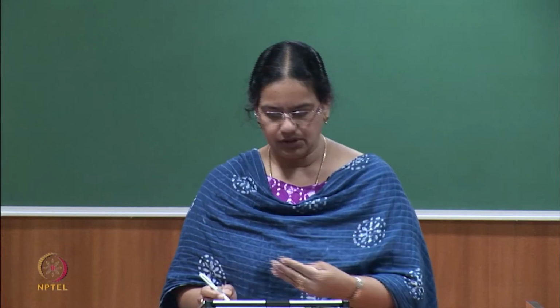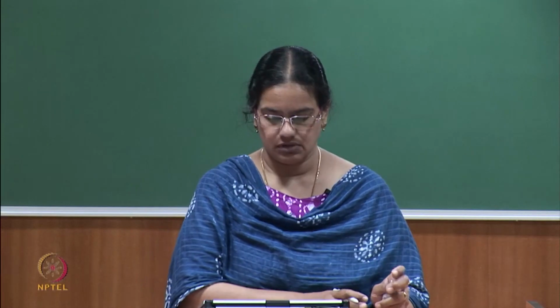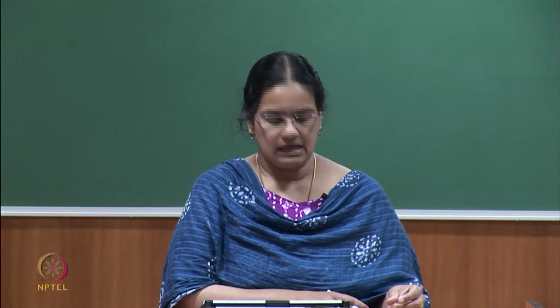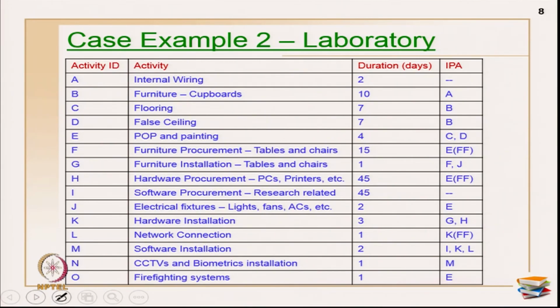Now, before coming to that, I said there is a prescribed time of waiting and so on. We have very nice examples for all these. For example, in concreting, curing is a very critical task. Instead of showing curing as one activity and connecting it with the finish start relationship, if you add the duration for curing as a lag, that shows it is taken care of, and it is understood by the experts that you have to leave 10 days for curing. That is the meaning of all these relationships and the lead lag combinations.